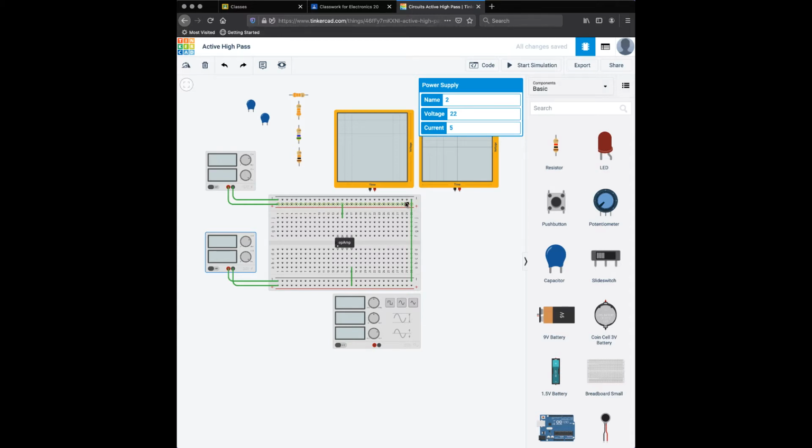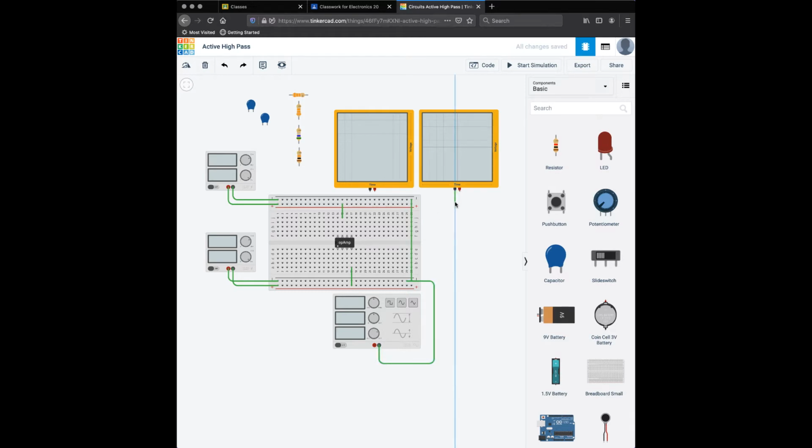To that end, I'm going to take my frequency generator here, and I'm just going to go ahead and connect it to ground, do things as neatly as I can, although I have to work somewhat quickly. I can rearrange these, make it look pleasing. So the frequency generator is connected to ground. Here's one of my scopes. I'm going to connect this scope to ground right there. Stretch that out a little bit, make it look nice. I'm going to connect this other scope to ground right there. That's fine. Connected to ground. Okay, so everything has the common ground.